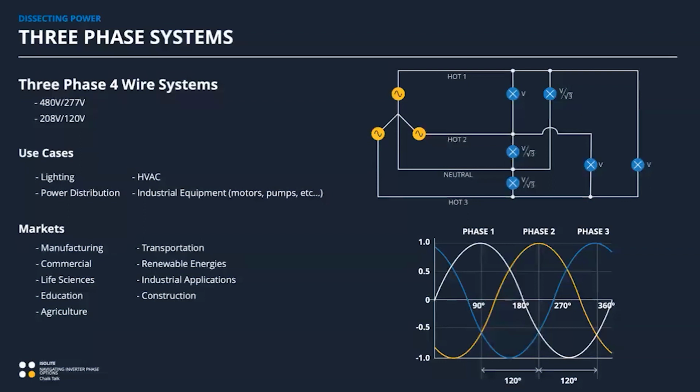Now, this is definitely the most common for commercial installations. It's sort of tied in our inverter offering for what's the most popular, three-phase versus single-phase. But really, almost every commercial building that you see is going to have three-phase 480 power coming in. And the reason why we say it's 480 is that it actually makes 277 as well. You can kind of get into the math here.